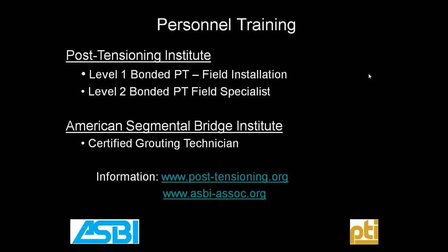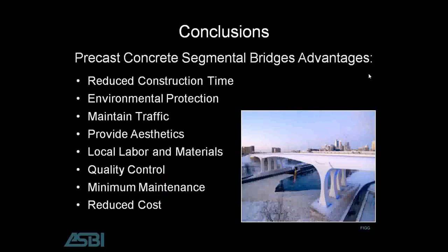For personnel training, if you have an interest or see the need for experienced personnel, the Post-Tensioning Institute offers a level 1 and a level 2 bonded PT certification. Their level 1 is the basic, for field installation. The level 2 provides for a post-tensioning field specialist certification, and that's generally the superintendent or the foreman for the job. The American Segmental Bridge Institute also offers a certified grouting technician certification. If you'd like more information about this, there are the 2 websites, PTI's website and ASBI's website.